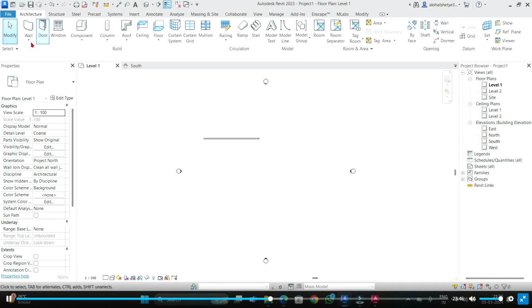So architecture tab, as you can see, your building element, whether it's a wall, door, window, roofing, floors, okay, your circulation elements, your staircases, railings, etc. All the commands, direct commands are specified here. So you can use these commands to model your project, to model your structure. Yes, whenever you're modeling, it's not just 3D modeling, remember, it's information modeling. So you have to input all the data. So it might be your materials, the layering of the walls, the costing of it, the non-graphical data, properties, right? So everything needs to be input. So that's how your modeling would work.